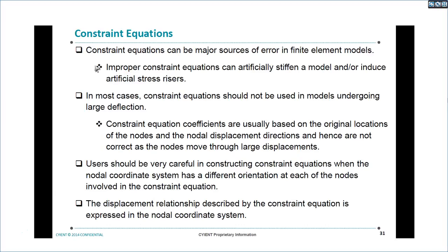And some important information on constraint equations. Constraint equations can be a major source of error in finite element methods. An improper constraint equation can artificially stiffen a model or induce artificial stress risers.